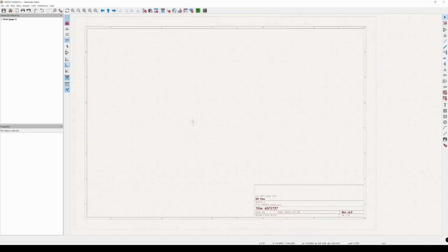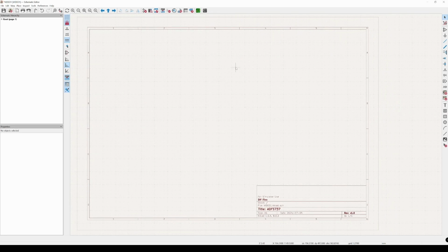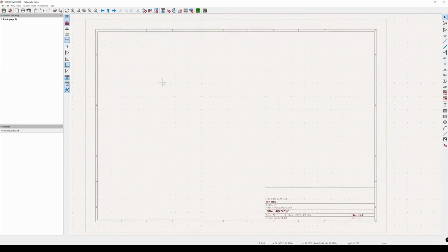But now, what you want to do first, after you can use the interface, is of course add a new component. And add a new component by clicking here on the right hand side, add symbol. But you can also, and I highly recommend you learn the shortcuts, click A, and that automatically opens the symbol libraries for you. It just loads them in.